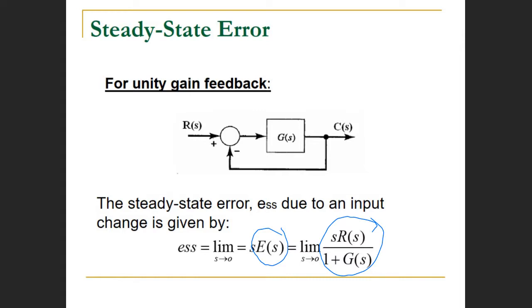Could you use the block reduction method, sir? All right, so you're proposing block reduction. How would you do that? You want E of S. That would be G of S over 1 plus 1 times G of S.